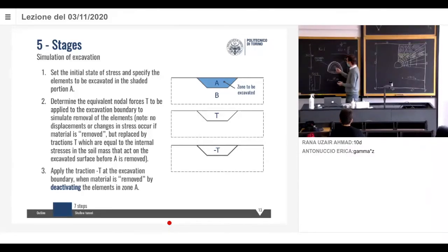Because when we do step number one, excavation, we can put an internal pressure, and then we can remove it to make a full excavation. But when we remove it, we can put the primary lining, for example. And in that case, the primary lining is going to get P0 minus Pi, and so on. So we'll go into it. I went through it quickly, but now we're going to do it slowly. Okay, I see some faces. Maybe those that haven't gone through rock mechanics are a bit disoriented. But we'll go into it.